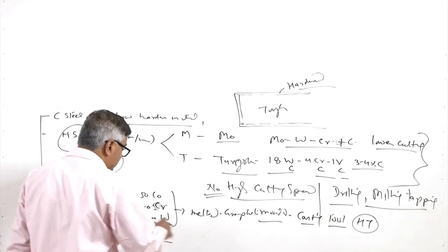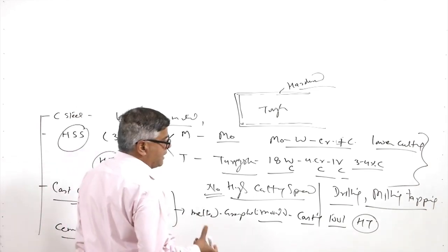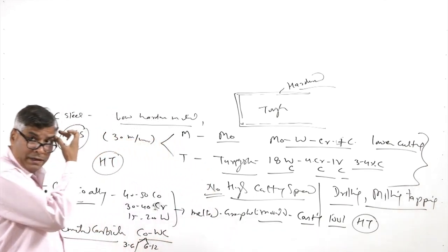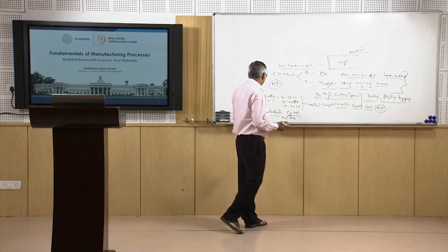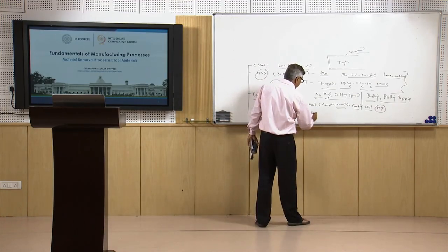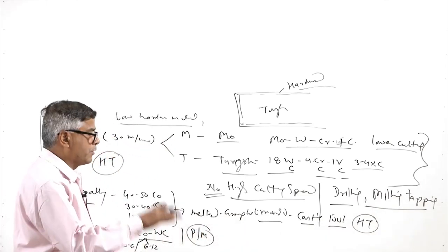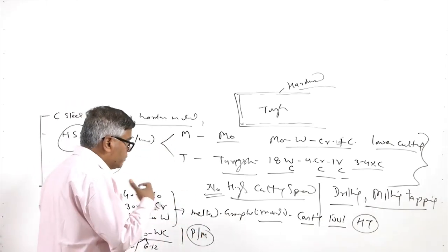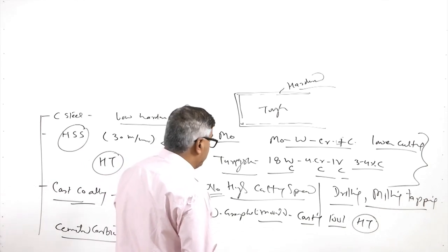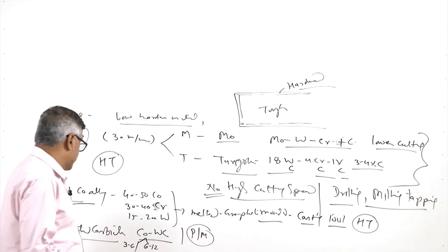So, accordingly we get the higher hardness or the lower hardness. Cobalt is used as a binder, while the tungsten carbide particles will be there as a reinforcing agent, and these are produced through the powder metallurgy route, wherein the elements in powder form are compacted, then sintered to get the shape in the desired form of the inserts, so that they can be used for the cutting purpose.